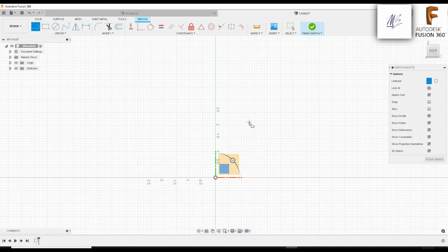All right, so you have the cursor here, left click on the origin, kind of drag it up. Now you see how the number, the inches, is highlighted in that little box. You want to type in the depth of it, which is 4.5. It's going to lock it. You see the little padlock popped up? That's our first constraint. Left click line, do the same thing, but we're going to drag it over this way.